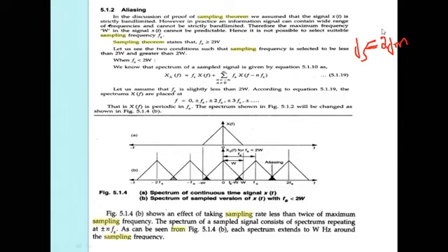It is not suitable to select an arbitrary frequency Fs; the sampling theorem states that Fs is greater than or equal to 2 omega 1. Let us also see the two conditions where the sampling frequency is selected to be less than 2 omega and greater than 2 omega. When it is less than 2 omega, an overlapping occurs, which is nothing but aliasing. Okay, let us see.